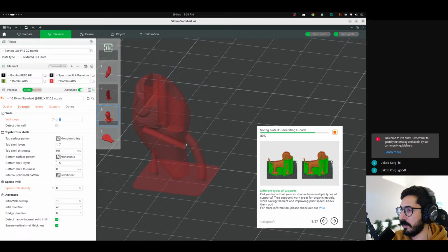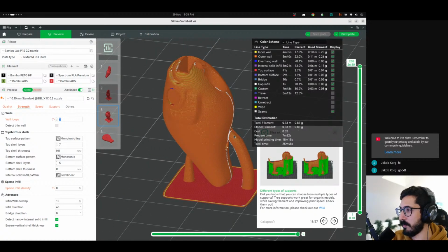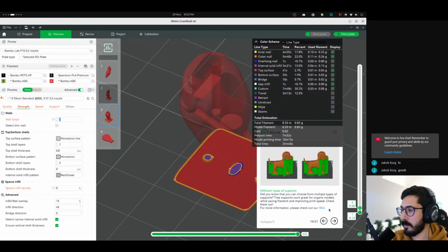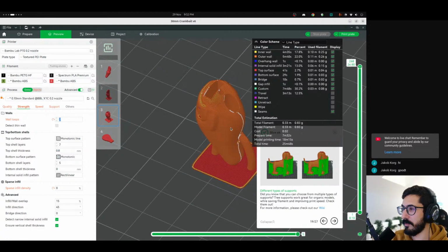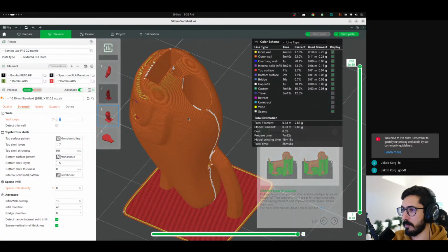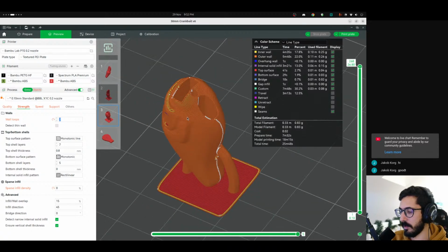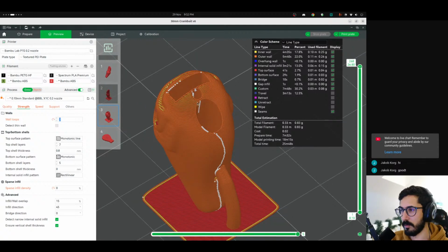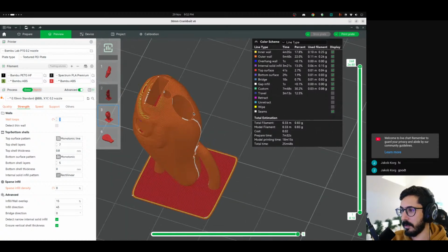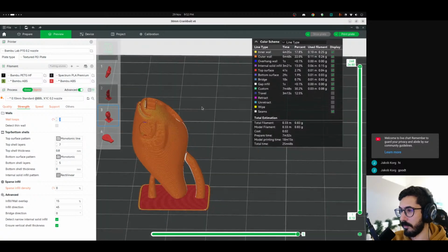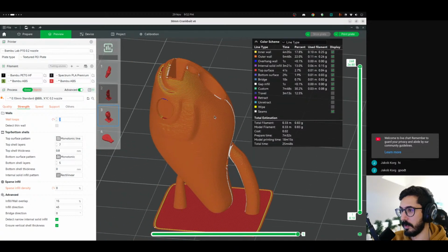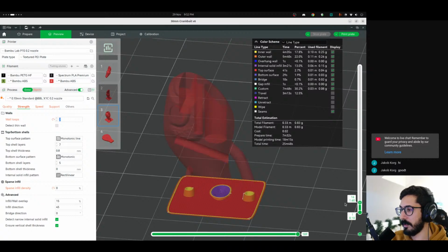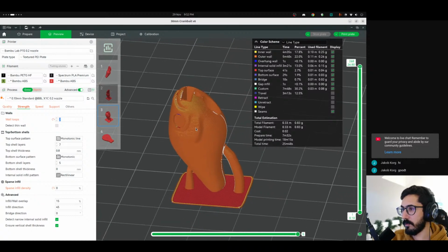So if we remove this, it's already 0.8, but it's gonna be very, very brittle. So it might break very easily. And the screw eyes or the twist wires might just pull up or split the lure in half when you catch a fish. So as you can see, this is not very feasible this way. So how do we do that?